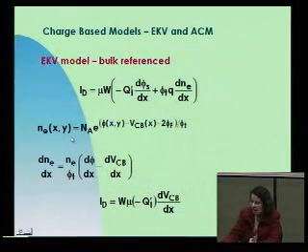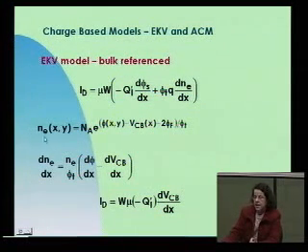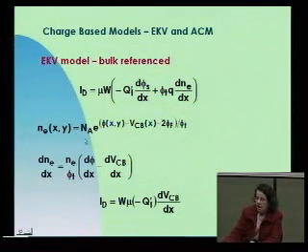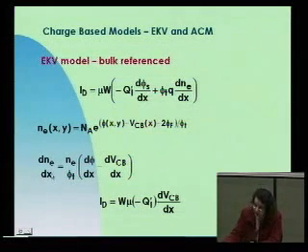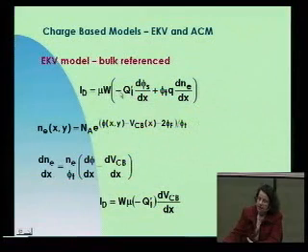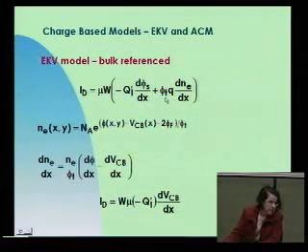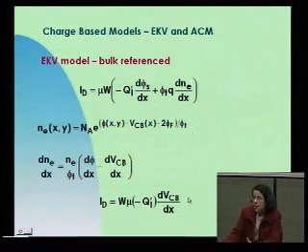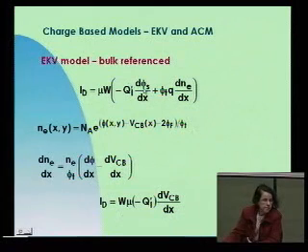It comes from the differentiation of the electron concentration. If you differentiate with respect to X the electron concentration, and remembering that the inversion charge density is the electron concentration multiplied by the electron charge, you have this, because this term will cancel with this term.